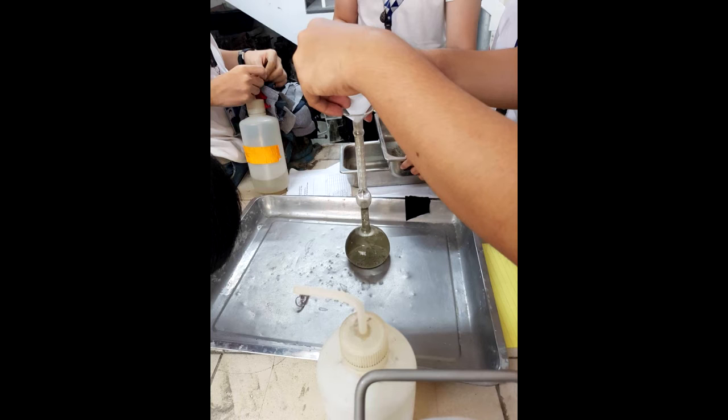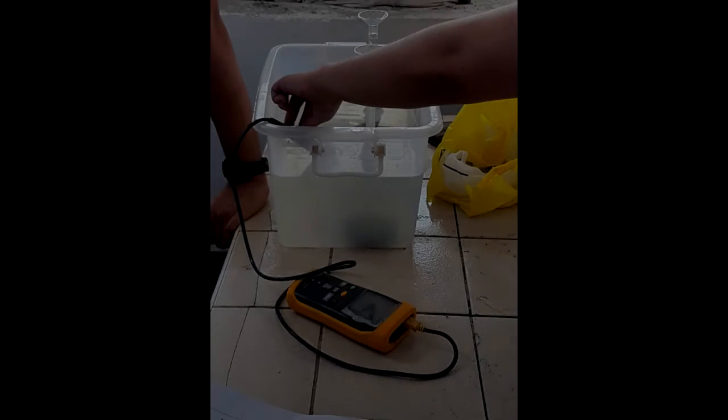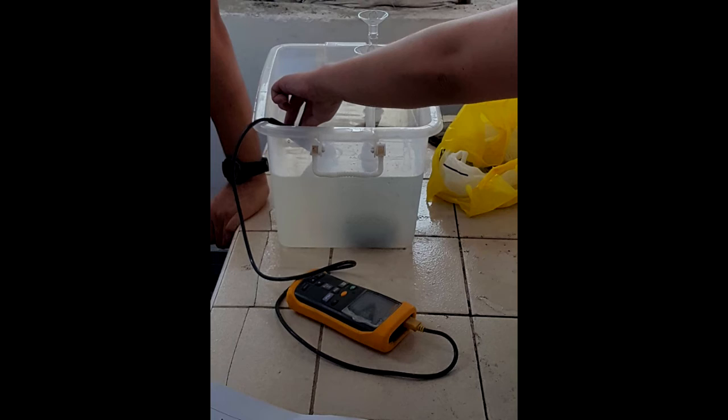There are some considerations to be made when performing the experiment. One is to always make sure that the flask is clear of any water. When the group was ready to add in the cement, they found out that there was a single droplet of water under the flask. This means that they had to repeat the whole experiment, or else the cement would have hardened inside the flask and eventually broken it. So it is always important to be aware when dealing with the flask, especially during the cold bath.